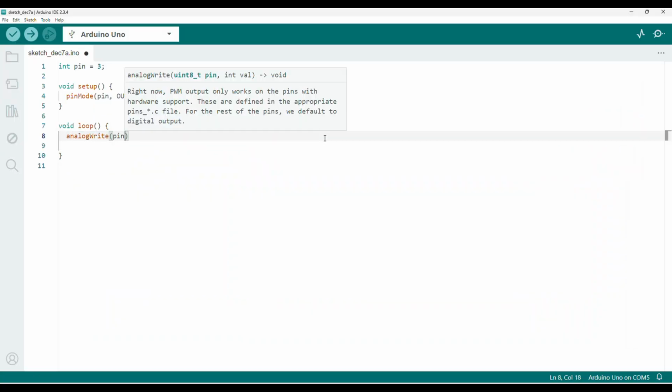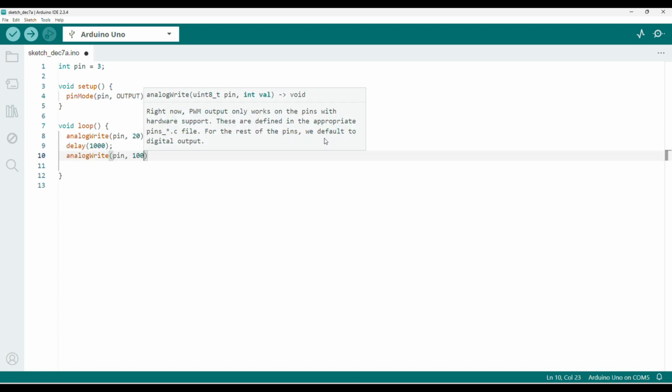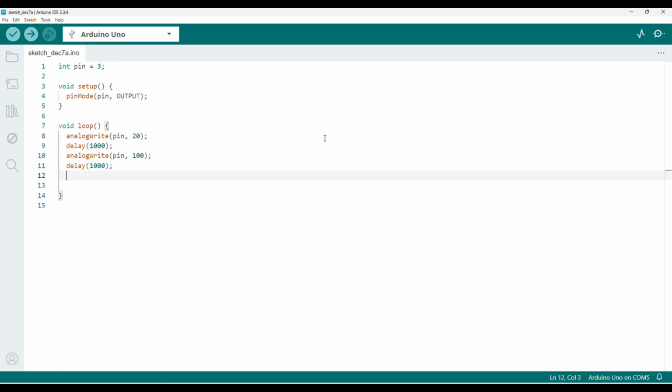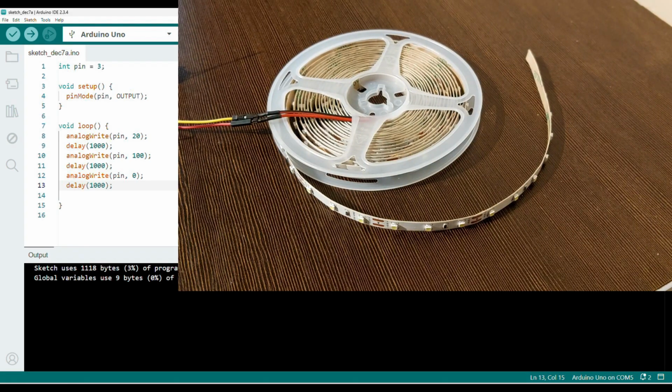Okay, addressable LEDs are pretty spectacular, but also the most expensive ones, so probably more often you will opt for monochrome or RGB options. And as they don't have this built-in power control circuit, you need to provide one yourself. From code perspective, it's pretty easy. You just need to use analog write function, setting desired value on relevant pin, and microcontroller will use pulse width modulation to reduce the brightness on given channel.